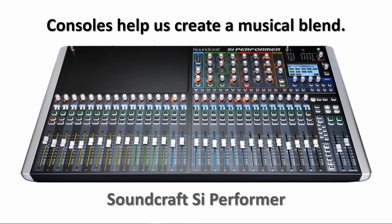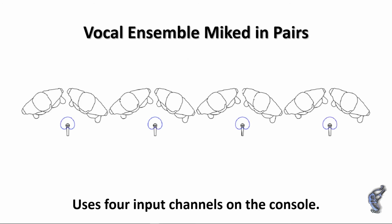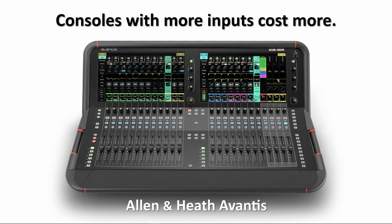Consider these scenarios. Let's say that we're miking a vocal ensemble of 8 vocalists. We could pick up the entire group with one mic and let them blend themselves. Or we could let groups of 2 or 3 vocalists share a mic. Or we could simply hand each vocalist their own microphone. Sometimes it helps to use fewer inputs and let people blend themselves. The trade-off is that more mics means more inputs on the console, and consoles with more inputs cost more.